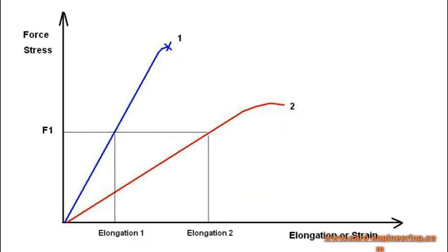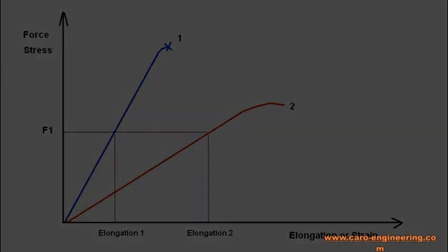We can show this relationship also in the stress-strain curve. Material 1 has the higher E modulus. It stretches less under the same force. Material 2 is a softer, ductile material that yields before breaking. Because airplanes must not deform too much, we need to select materials with high E modulus in its construction.